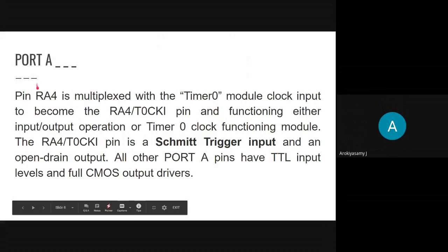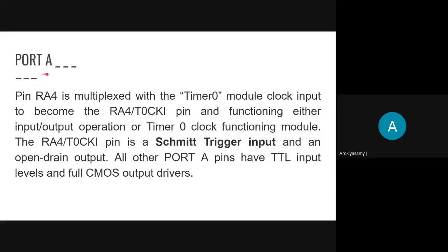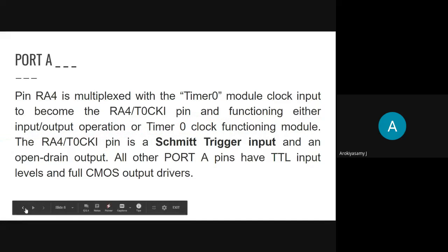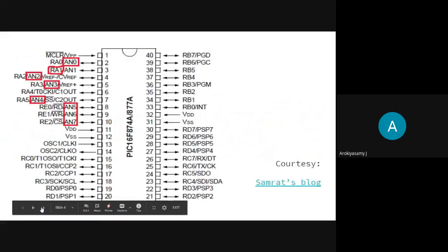Okay, port A discussion. Now we will continue the discussion on port A pins. Pin RA4 is multiplexed with the timer 0 module clock input to become the RA4/T0CKI pin and functions as input or output, as I already told you. See once again the pin diagram. The pin diagram is very important.